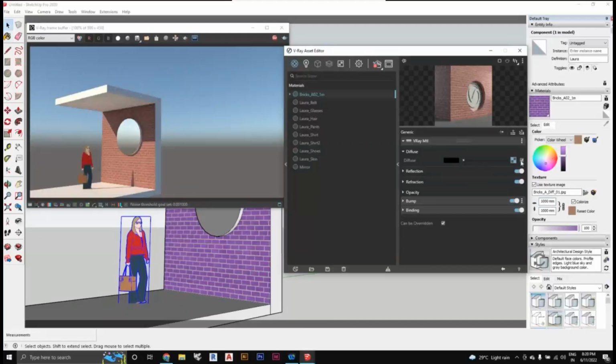There is a color option, and only one of the two will be shown at a time by V-Ray. So if you want to change the color of the texture, there is a small box with two black squares. Right click it, go to wrap, then come to color correction.